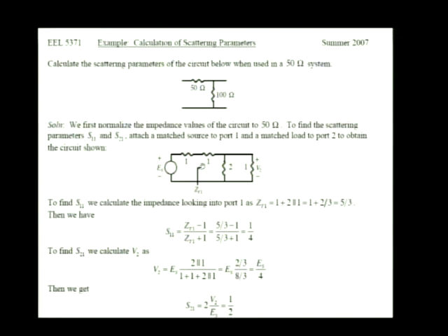That is to say, back up here in the original circuit, imagine putting a 50 ohm resistor here on port 2 and asking the question, what's the impedance looking into port 1? That's ZT1 that we're talking about in our equation for S11. Okay, well that's something I could hand to a student in a Networks 1 class.